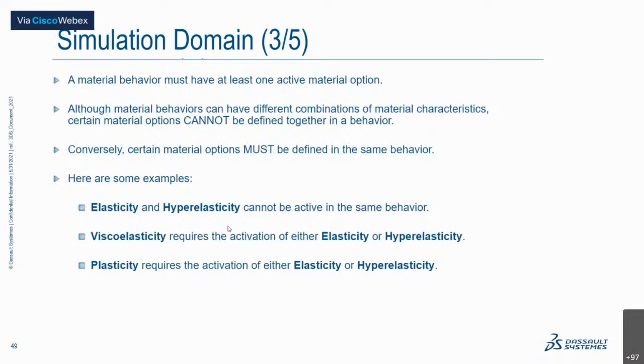While on the other hand, you'll also have to for sure define multiple behaviors in order to get a behavior. For example, viscoelasticity. In order to give the viscoelastic behavior for a given component, you'll have to enable the elasticity or the hyperelasticity. And similarly for the plasticity too. So without defining the elasticity component or the hyperelasticity, you cannot define the plasticity value too. So these are a few tips that you could follow.